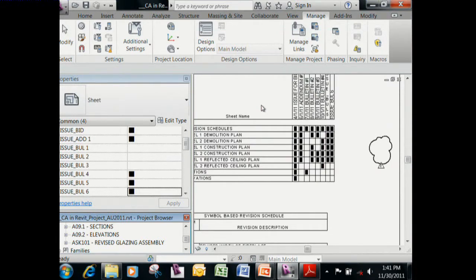revision column within the schedule. And then what you could do is just use text off to the side within a door schedule sheet and call it a little area that says revision items or something like that. You number it, say number 1 is door 237 has been deleted, and then you key in number 1 into that particular issue. So when you make changes in the future, it's always going to stay in that column and stay in the row associated with that door, and you'll have a history of the changes that were made.